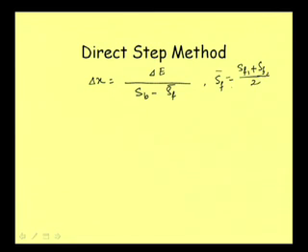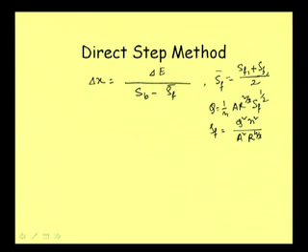Now, what is SF1? We can write Q is equal to 1 by n A R to the power 2 by 3 SF to the power half. So, SF we can write as Q square n square divided by A square R to the power 4 by 3. Knowing the value of depth at a particular section, everything else is fixed: Q is fixed, and n, if we consider it constant for any depth or section, because roughness is not changing significantly.